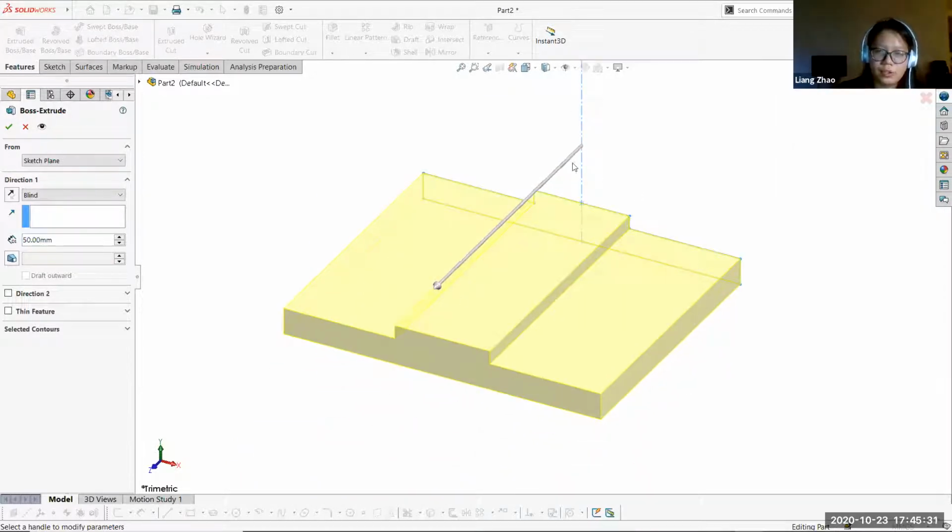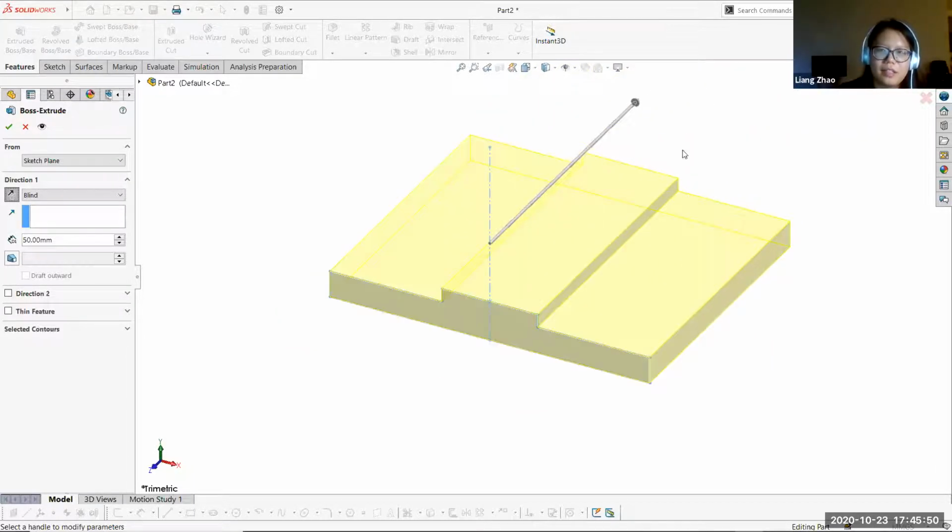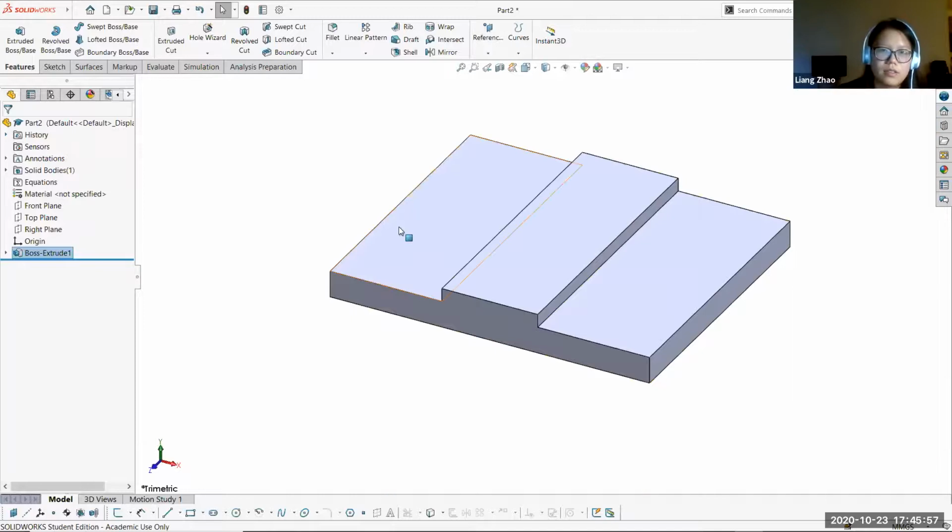It feels kind of awkward for it to be extruded in this direction, because if we want the mirrors to be this way, we can just use the mirroring of this plane. And also the origins here. So for isometric view simplicity purposes, I'm just gonna flip it. But either way, it's fine. So I'll click the check mark since all the dimensions are correct. And move on to sketching the holes on the top face.